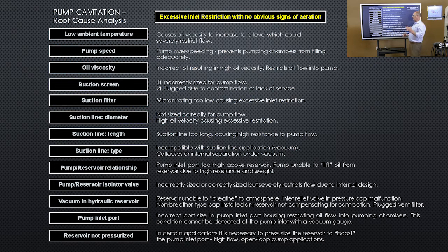Next, the relationship of the reservoir to the pump. By rule of thumb, a pump should never be mounted more than 3 feet above the oil level. So that could be a problem.